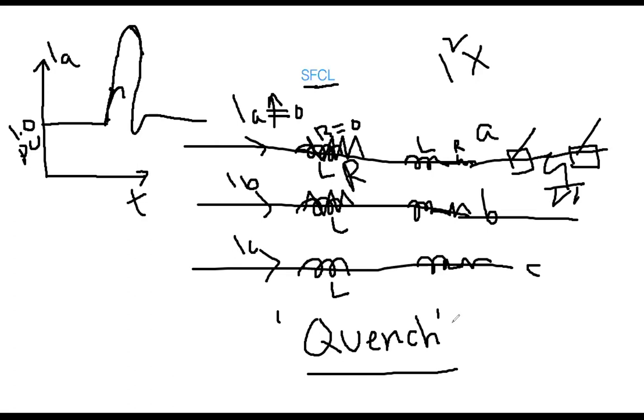Now the question is, as I said, that quench occurs and then it takes some time to get back to that superconducting mode. By then, the circuit breaker opens and closes, and assume that still this coil is not fine, it did not return back to that SFCL mode, but then again another fault happened along the line. So therefore it may happen that once the fault happened, because it is not anymore that superconducting fault current limiter, it may not help.